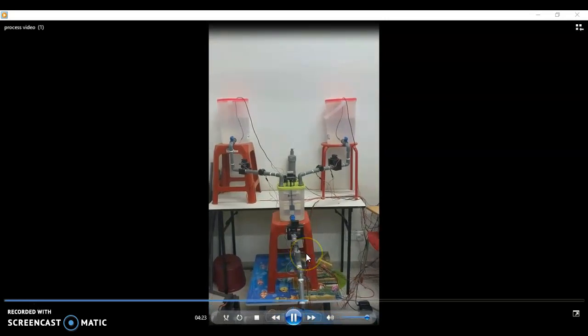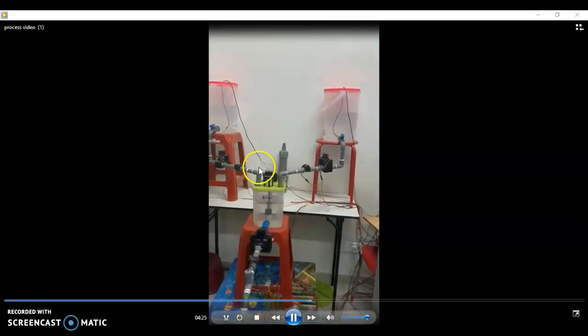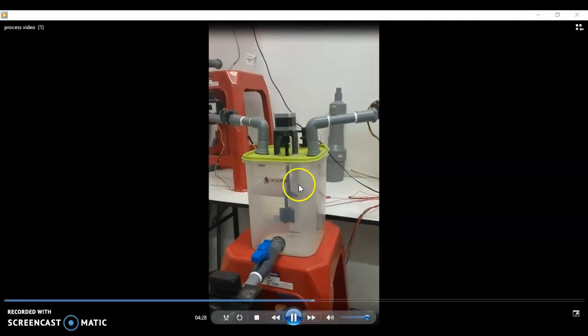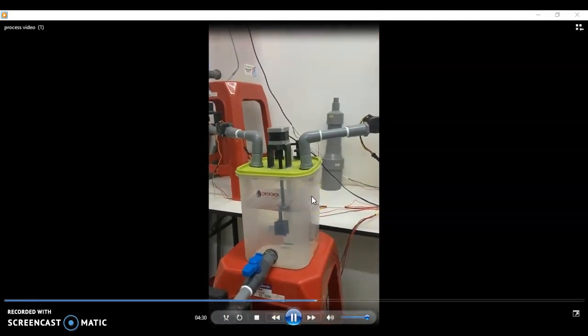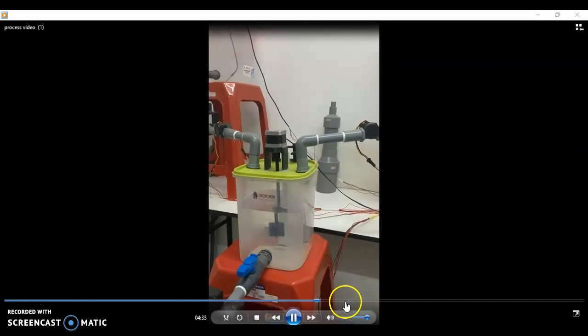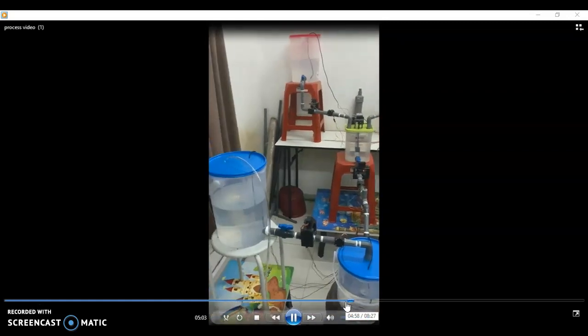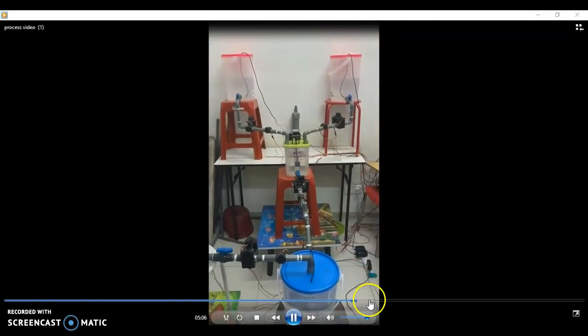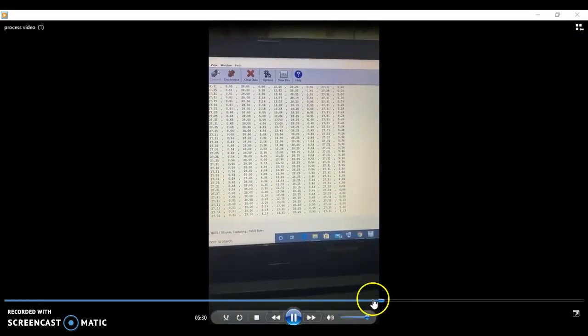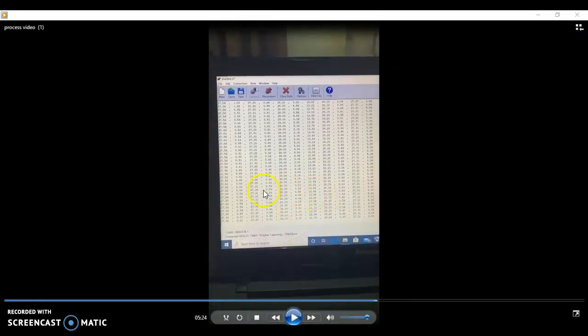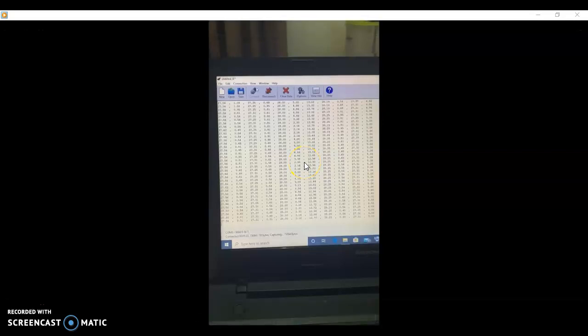After that, I reach a steady state in which each flow and each variable in the process is controlled. So I don't have to do anything. The process is controlled fully by the Arduino and the control valve. During that, as you can see, I can get the data. I basically have 12 input data from 12 different sensors. This data will be read and sent to MATLAB. I already developed a MATLAB code that will show the data and draw them in different graphs.